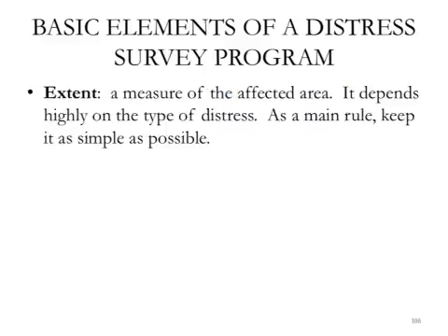The other aspect that we need to keep in mind while we are in the field observing distresses is the extent. Because I may have a very severe fatigue crack, but that crack might be one single crack, not covering the entire section area. So in order to have a full understanding of this distress, we also have to mention and measure the extent.